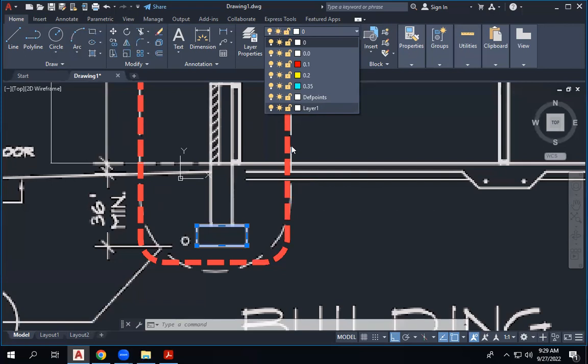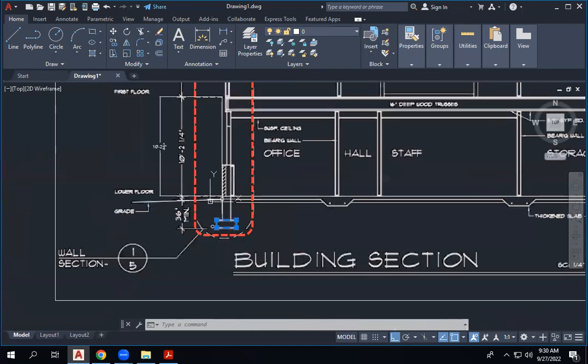Don't try to draw everything in this one as it is. You just draw the basic lines. What we want is the line here. You need to know that there is a slab here. So we will have one continuous two lines here, continuous two lines here, and the foundation like this, and the wall. Just draw the wall as two continuous lines. That's it. So we will detail it later.